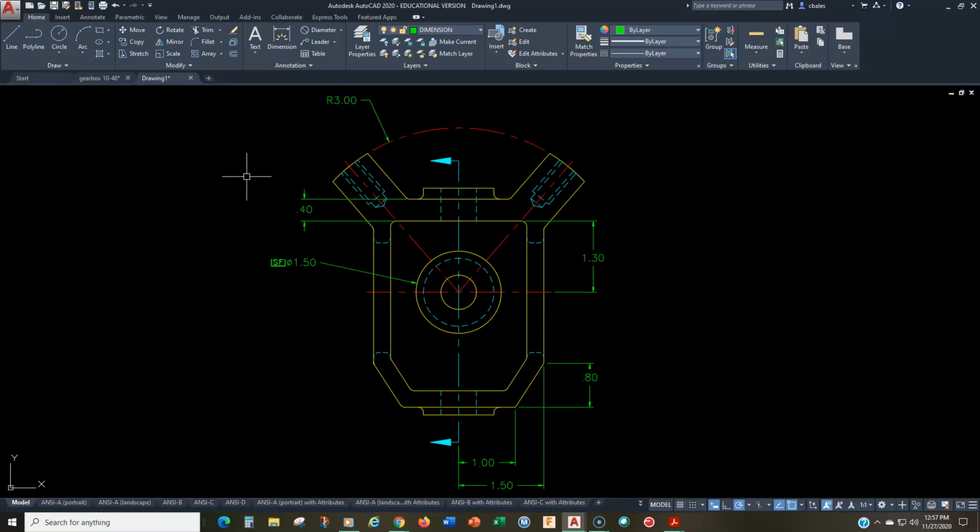So we're not going to talk about substyles or dimension children or anything like that. That's, you know, for the Intro to CAD class or a larger discussion. So the rule is here, use Match Properties. Change one dimension and then use that as a source to change the other dimensions. Separate your diameters and radiuses and do those separately. Okay? All the other dimensions can be done the same. If anything screwy happens, just undo it and redo it. All right. Now, so that's changing the number of decimal places.